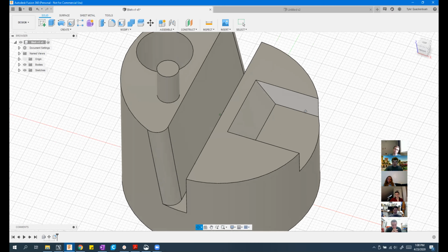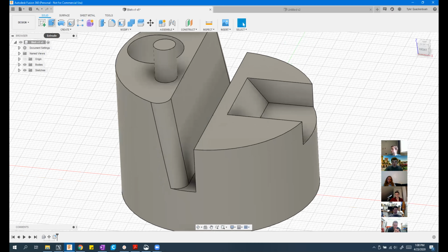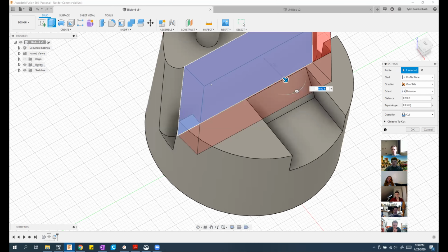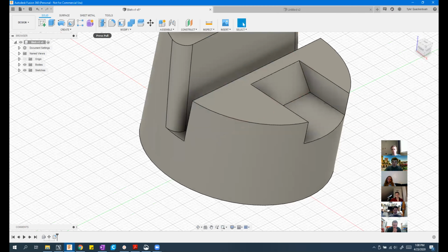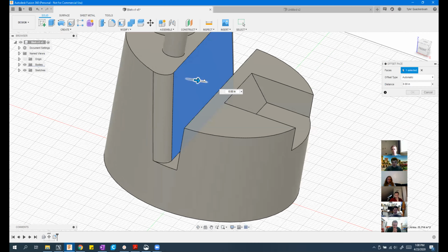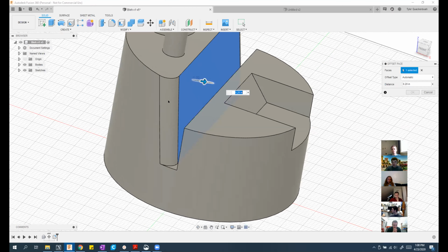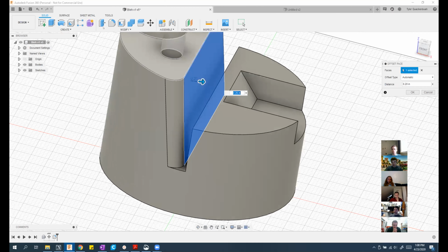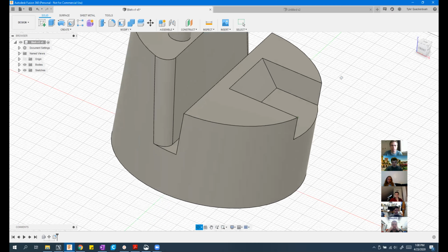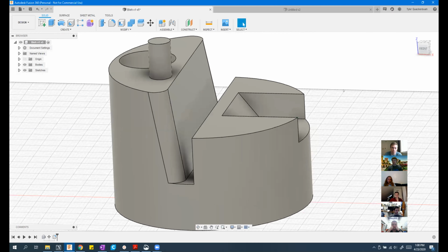And then, interesting thing I learned too, so you can extrude a face directly, and that does about what we'd expect. It takes that face and it extrudes it directly out. I was confused about where press pull differs. If I try to press pull this, it'll bring those fillets with it, and it'll try to preserve the geometry as it exists. So press pull is one that's interesting to work with, and move copy is one that's interesting to work with. I'll show you all one more trick too that they talked about that's really useful with pulling in imported geometries.